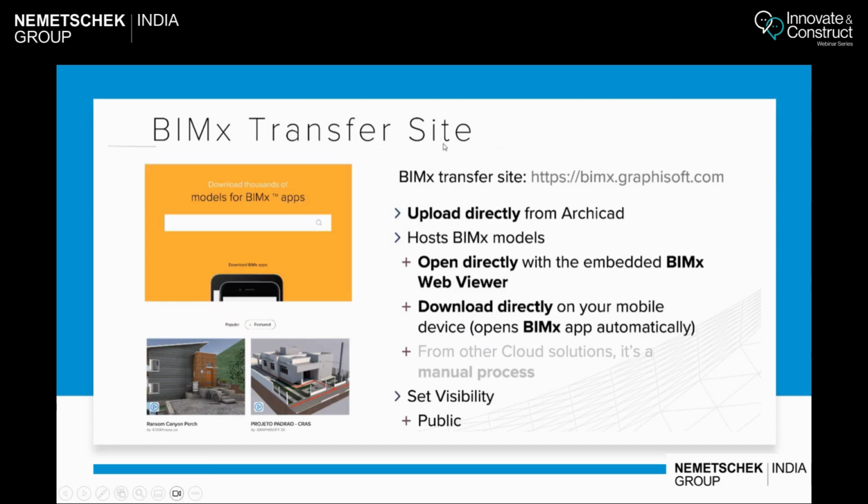So BIMx transfer site is the BIMx model hosting site, where I can upload directly from Archicad, like we just saw the settings for it, or I can also upload directly from my browser if I have any BIMx models in my local storage. So this BIMx transfer site hosts all my BIMx models. I can open directly all the BIMx models from the web viewer. I can also create a link and then share it with my clients. Or I can also open the BIMx model and download models directly on my phone or my desktop and then open that particular model using the BIMx app.